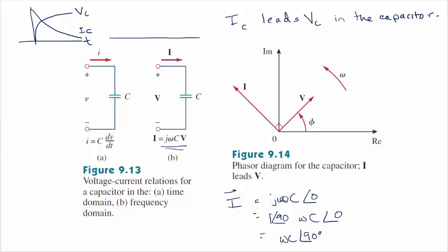And so in time, with an AC signal now rather than a step response, voltage in the capacitor could be doing this, and then I leads V by 90 degrees. Let me try to draw this nicely. I would cross 0 first, in this phasors-rotating-around-an-origin description.